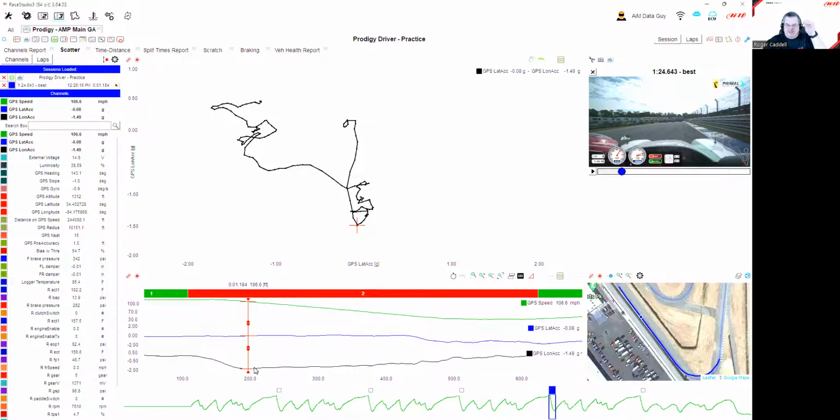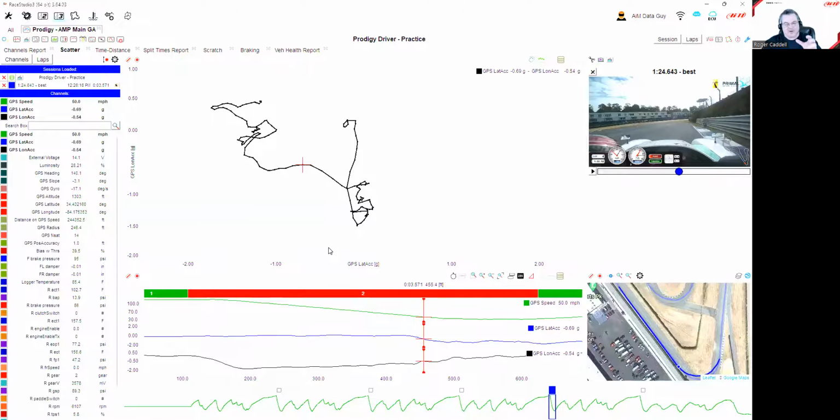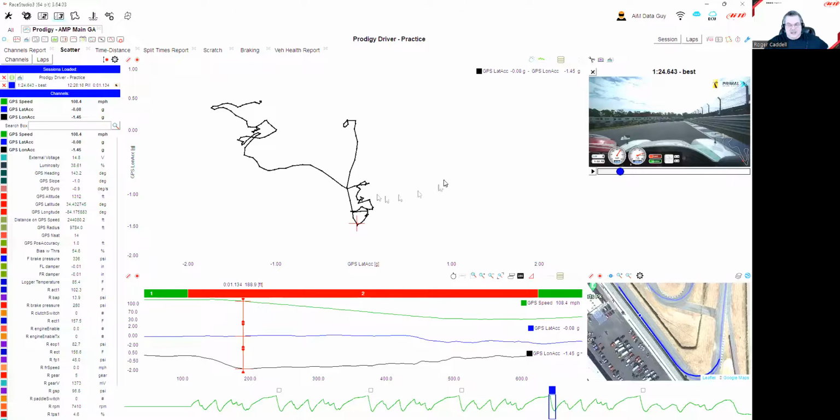I would love to see if the braking was more come down here and sit down here. That braking longitudinal G should be flat, and then start the trade longitudinal for lateral. But the driver did it by releasing the longitudinal a little bit just as he starts to turn in. But what this gauge, some people will call this the display that shows you your lost grip or lost opportunity. And we create these curved lines here that are, if we're right here, this is 1.5 G. This line is 1.5 G. It's curved because it's the way the data lays on it.